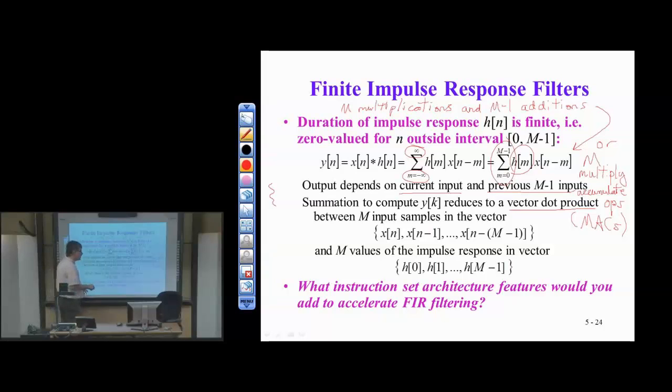The circular buffer has finite length, so if I need to know where I'm at, I look at the value of little m. I know what little n is. I know what little m is. And so what I need to do now is find where in the circular buffer that corresponds to. So I can always take n minus m, and I can do modulo. So this calculation is n minus m modulo capital M. This tells me where I am in the circular buffer.